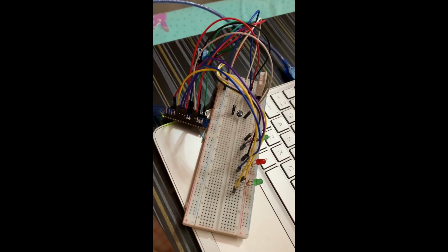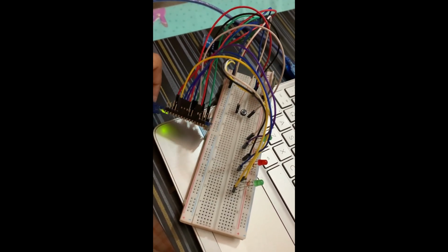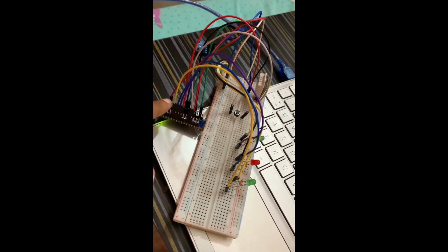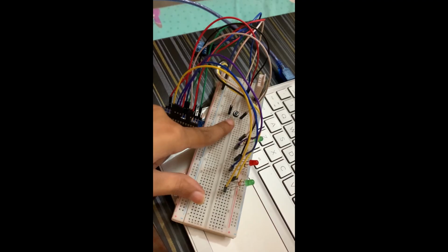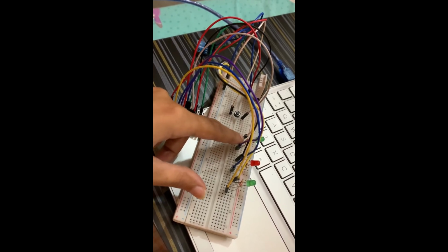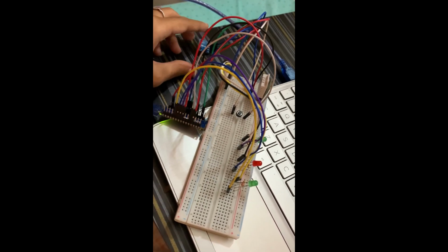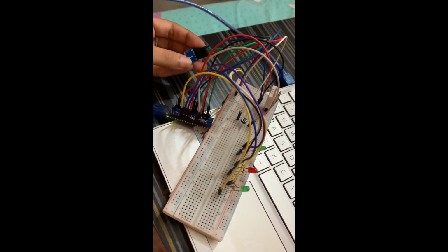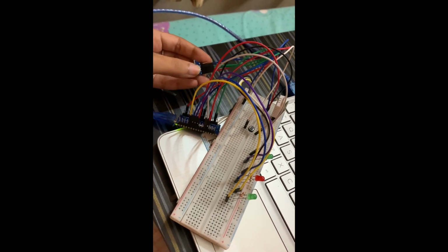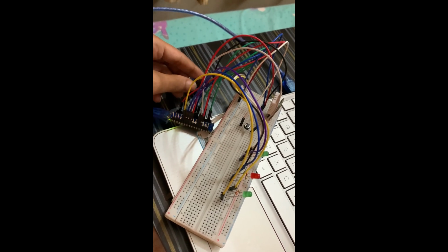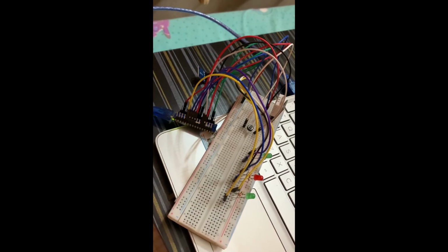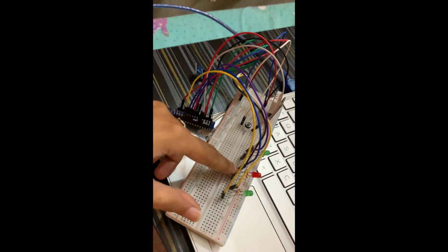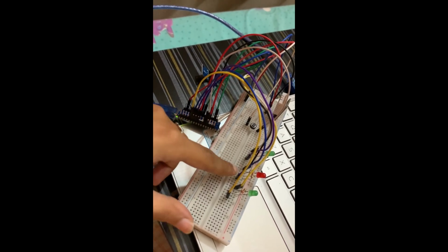This is my hardware setup. My project uses an Arduino Nano 33 IoT. A push button is connected to pin D2. When I press this button, it controls this green LED on pin D6. A light sensor BH1750 is connected to the board using I2C wires SDA and SCL. This sensor checks the brightness in the room and it controls this red LED which is on pin D7.